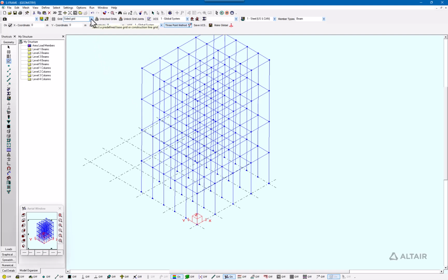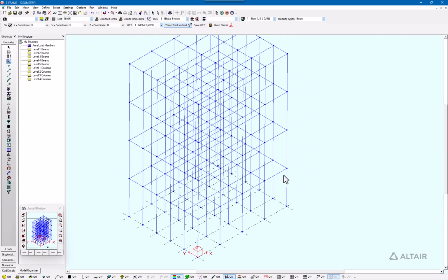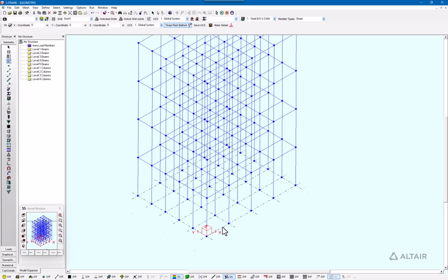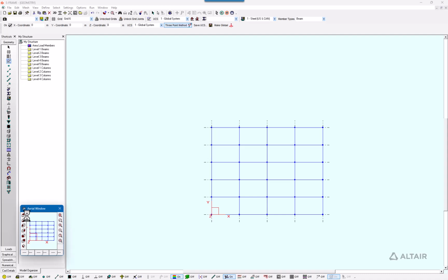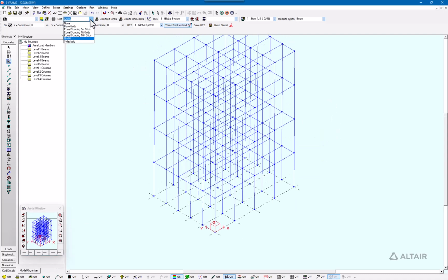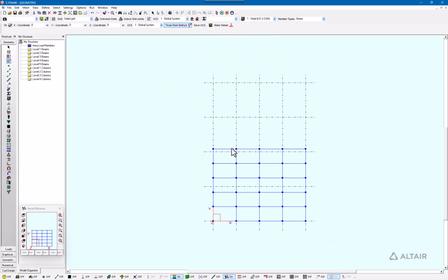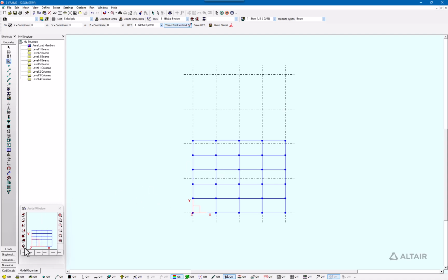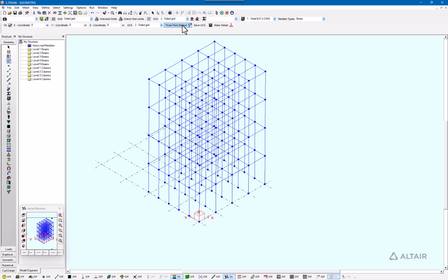So now I can just navigate smoothly with this list. I'm going to the grid number 6. It was defined initially. Now I can see here the grid that goes accordingly to this geometry in the top view. And when I select the sided grid, we can see this doesn't go with top view, but if we change our coordinate system, it will be with the side view.